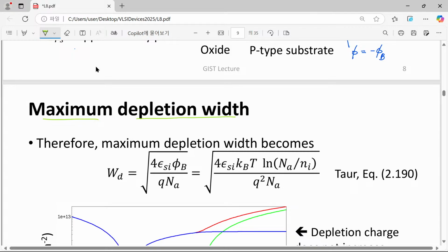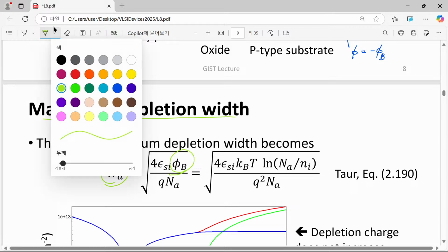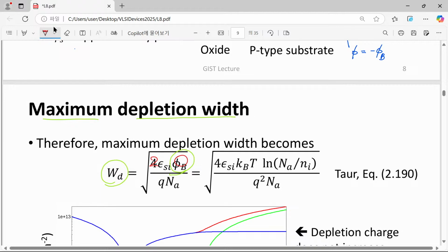It is because depletion width and surface potential, of course here we have two times phi s required, and phi s cannot increase indefinitely. For example, what is the maximum value of our phi s in our usual operation? Can you expect 10 volt in your surface potential? So you never expect such a high value.